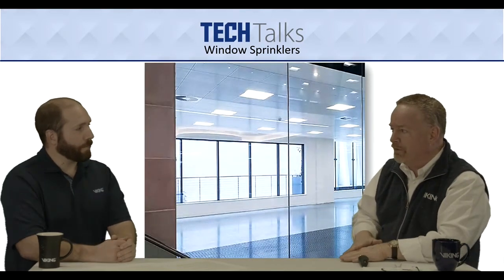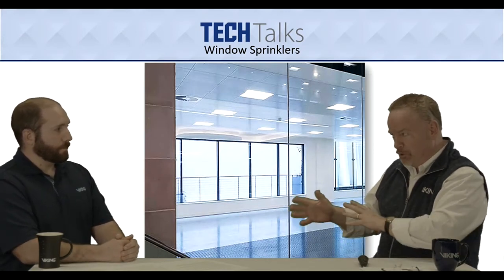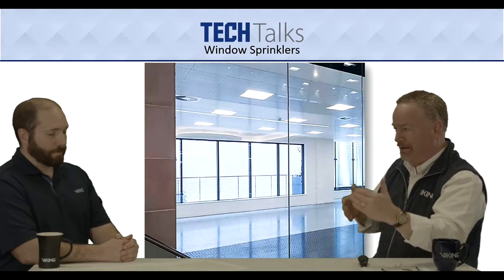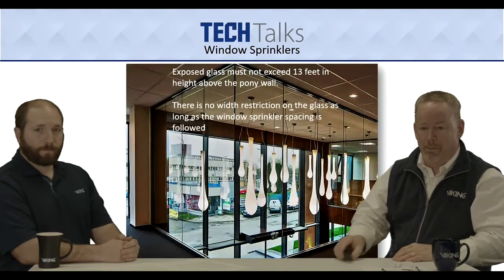So a couple of rules come along with this. What's really important, as it's getting evaluated, if you're planning on using these types of sprinklers, is that there are other rules that come along with this. In order to make this sprinkler successful, you also have to pay a lot of attention to the glass that's going in. Correct. You have to pay a lot of attention to a couple of things that come up here. So let's talk a little bit about that. A quarter-inch thickness. Yep. And heat strengthened or tempered glass, and single or dual panels. Correct. Right. So again, that's just the glass itself. Yep. Then we'll talk a little bit more about these two requirements here.